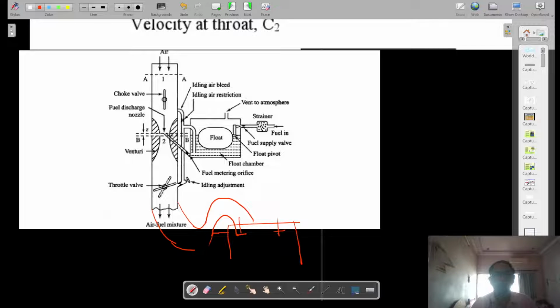This is just a line diagram I am showing you. This is the inlet valve. If the inlet valve is open, there happens to be a suction stroke. This is a piston; if the piston moves towards the bottom dead center, this is TDC and if it goes down it is BDC. The piston goes down, that means there is a suction stroke. When there is suction inside the cylinder, vacuum is created, and vacuum means pressure below atmospheric inside the cylinder.